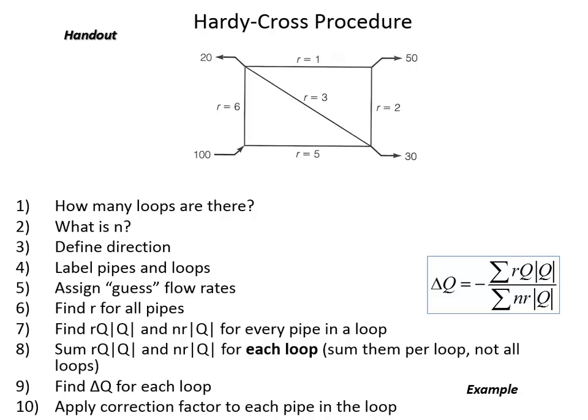What if you had just gone ahead and put 15 in and ran it? You still get the same answer eventually? No, it won't. It won't converge if you don't do that step. It won't converge if you don't make it negative when it should be negative, and it also won't converge if you don't use the most recent guess of what the flow rate is. Okay, so we can go through and do the same thing as before. Calculate each of these parameters. Negative 12.